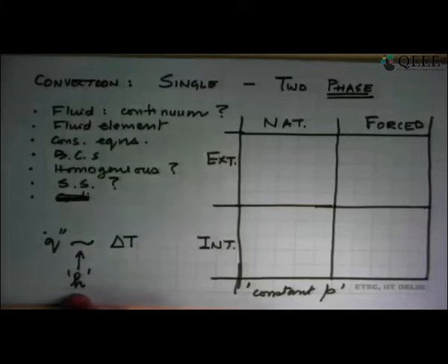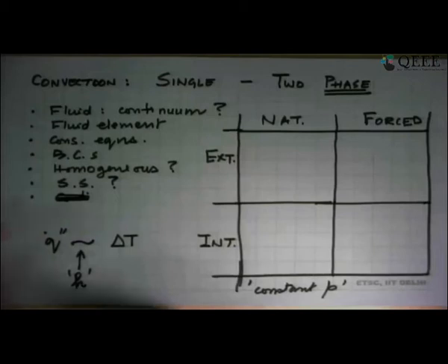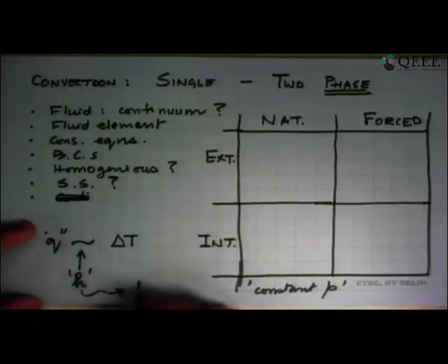And this could be the local one, which is over a small area, or the average heat transfer coefficient. Average because it will apply over the entire surface, while somewhere there could be a locally high heat transfer coefficient, and somewhere a locally lower one. So this is what we learned, that finally h depends on the fluid dynamics of the flow.